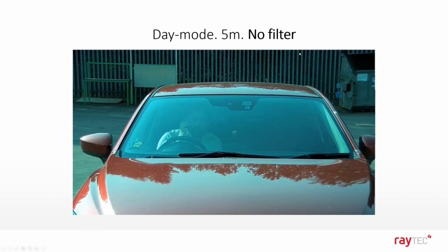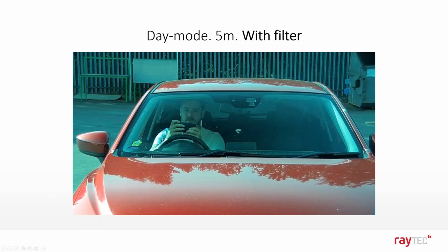So how do we conquer that? You add a polarizing filter. So this one here was just a cheap off-the-shelf polarizing filter that I used, and you can see the difference. We've went from that to that at a very low cost. So obviously to get the 24-hour surveillance, you need to consider not just the lighting side of it, but how reflection and things like that during the daytime. And that's at 5 meters.